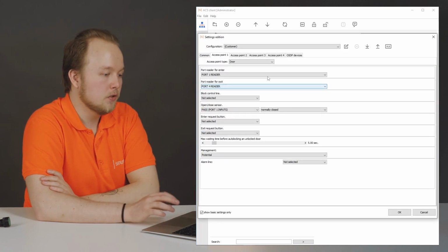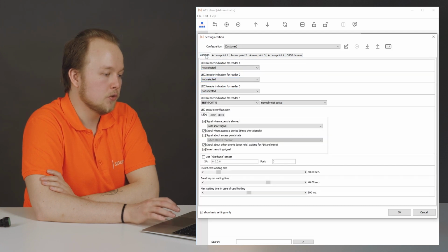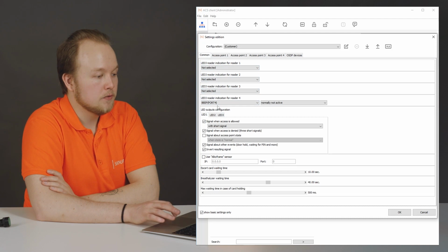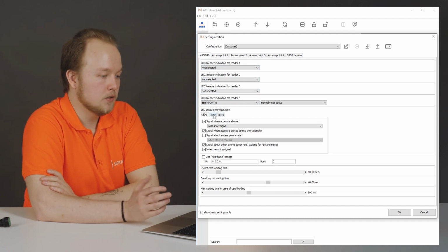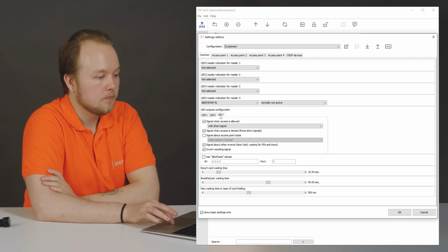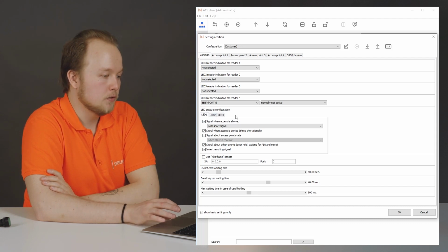In the indication control section, you can set logic for controlling light and sound of devices connected to the controller with a reader. Configuring the indication line for LED 1 and LED 2 is done on the respective tabs in the controller's config settings, as well as output terminals with reassignment performed to act as the LED 3 indication line. Let's consider the main parameters in more detail, considering that terminal LED 1 grants permission while LED 2 denies access.